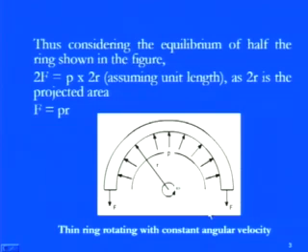This is the half portion which we are cutting, and in the half portion we can see that this is the radius of the thin cylinder. Since the internal pressure is exerting all along the circumference of this particular cylinder, we will find that these internal pressures are always going towards the outer circumference, because the centrifugal action is always dominating in this kind of rotating device. Due to that we have this pressure exerting, and we have the force acting on these particular cutting sections.